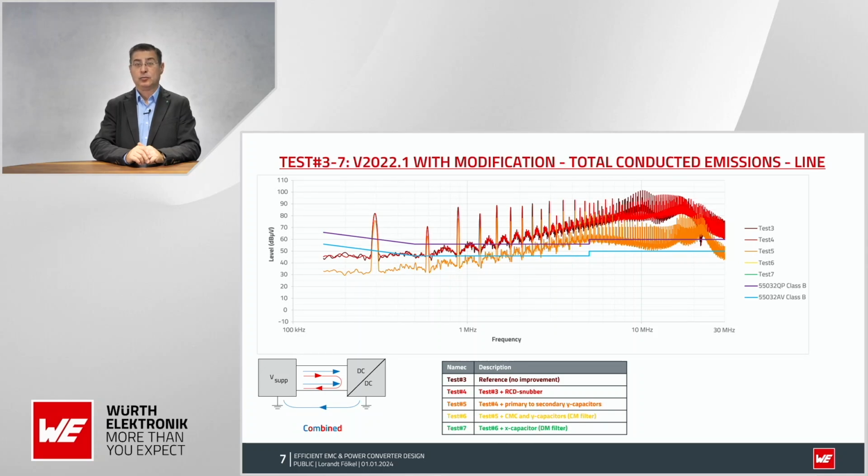So we take a common mode choke and the Y caps for that, and as soon as we place this common mode choke and activate the Y caps, we saw that everything above, I would say, 7-8 megahertz up to 30 megahertz is almost solved. The noise is dropping. It means that on the lower frequencies we saw just little improvement, even though the impedance of the common mode choke was there.